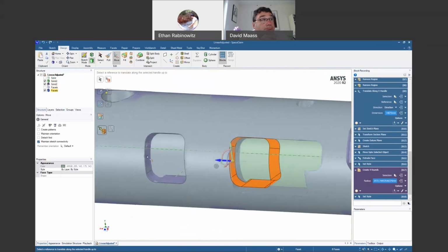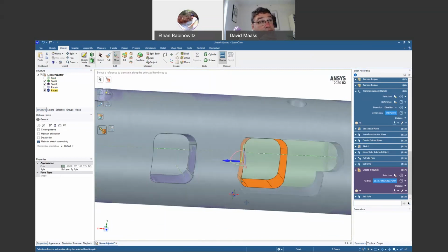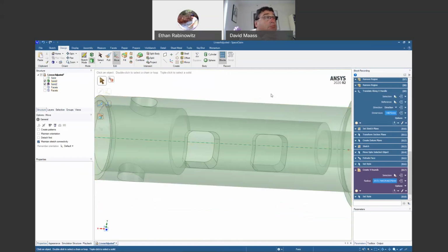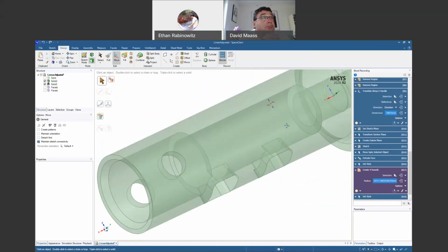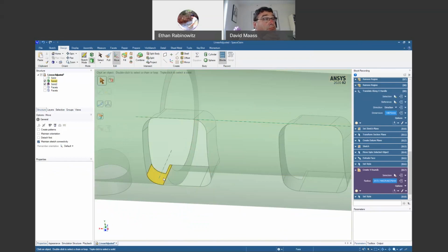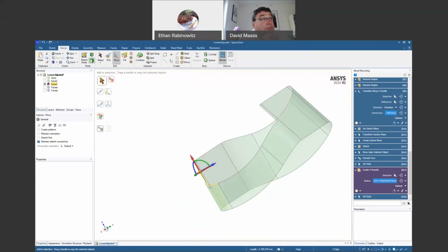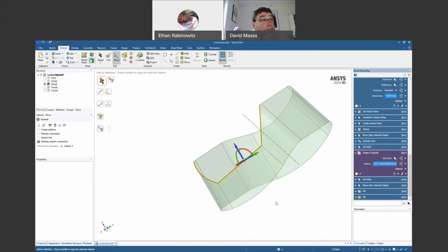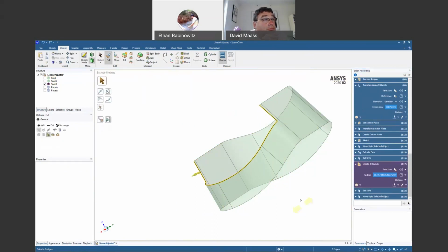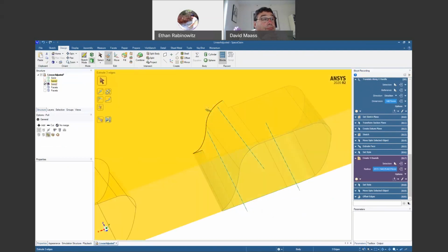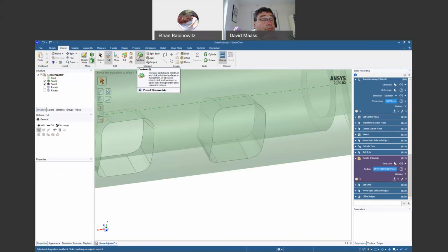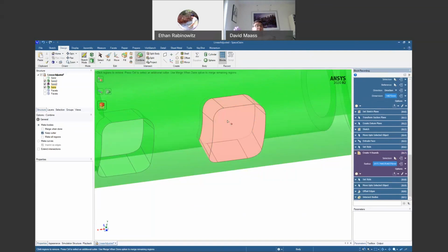So I basically picked a reference on the CAD body and then copied that to a reference on the scan body. So now if we hide the facets, the one thing that gave it a little bit of a hiccup, you'll see how there's like a cutout here, like it's not fully through. What we ended up getting was a copy of that just turned into a surface. So let me see real quick if I could heal this up and make our cut. There we go. So here I'm just using the pull tool. The pull tool you can actually use to extend the edges of surfaces. And now I should be able to do a Boolean, a combine, where this is the target, this whole surface body is the cutter, and then I can click on that piece to get rid of it.